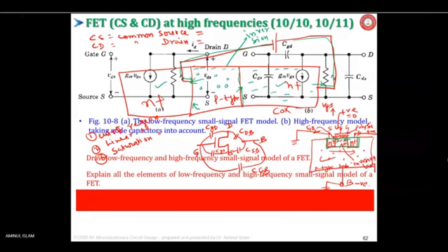Harsh Tripathi, tell. No, sir. It is not possible because this junction is reverse biased. Now look at the left junction. How is it biased? As I said, this left side N plus region is grounded, and the body is also grounded. So both sides are grounded, which means no potential is applied across this junction. Am I correct? Yes, sir.